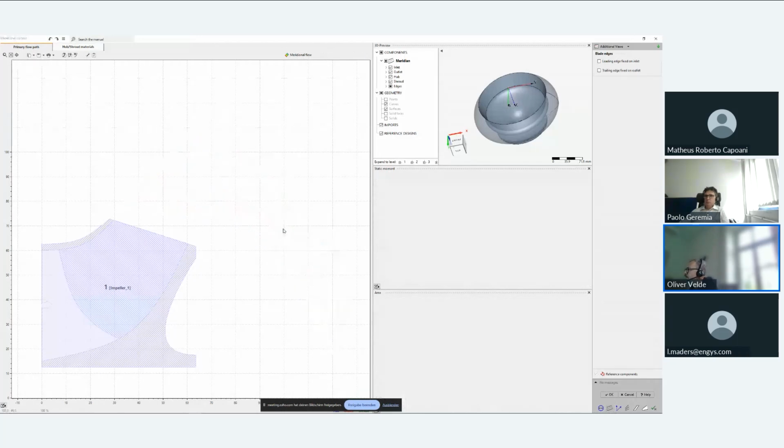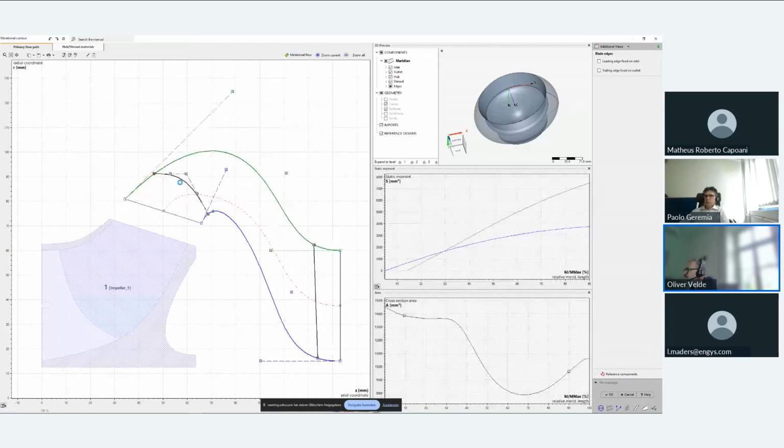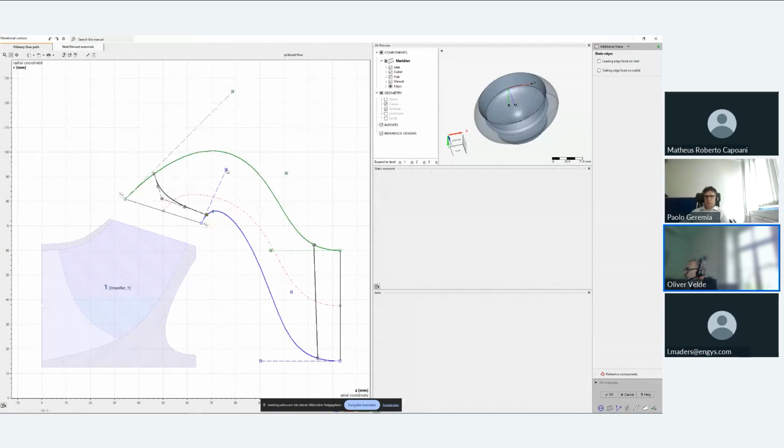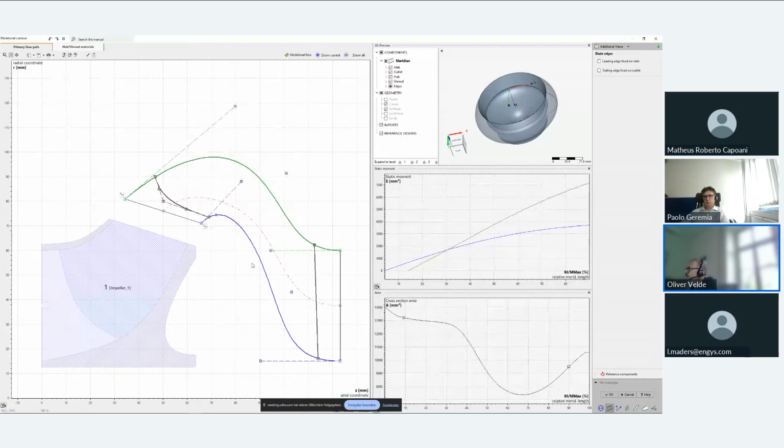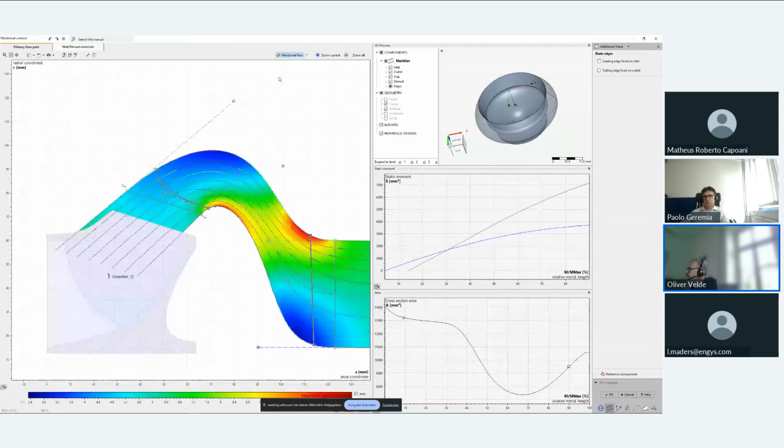I want to have the leading edge convex rather than concave, and that's why I'm going to change that a bit, and maybe change the hub contour a bit, giving it a smoother cross-section distribution. Again, we have this potential flow solution here. And again, after every change of the design, we get an updated flow solution. And that's, of course, only possible because it's potential flow in 2 dimensions.